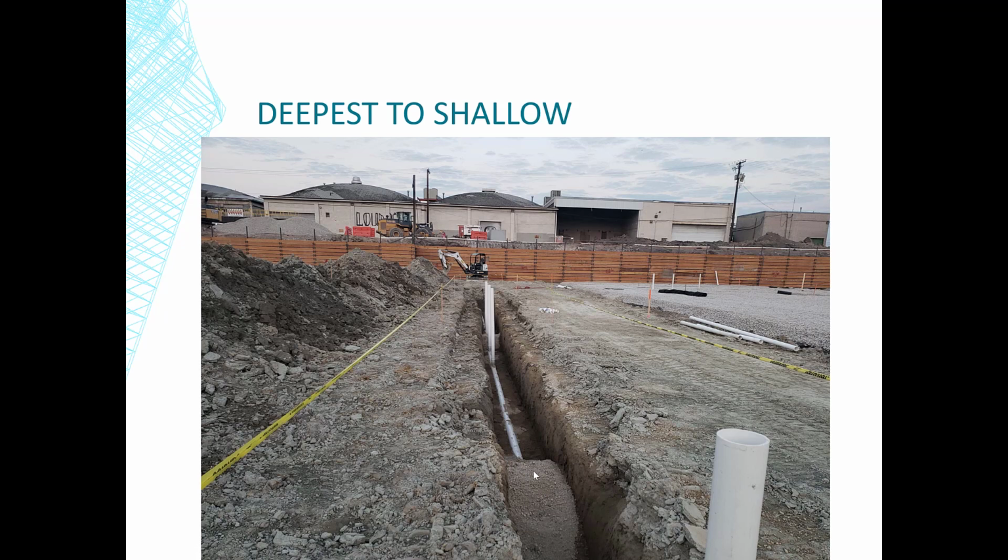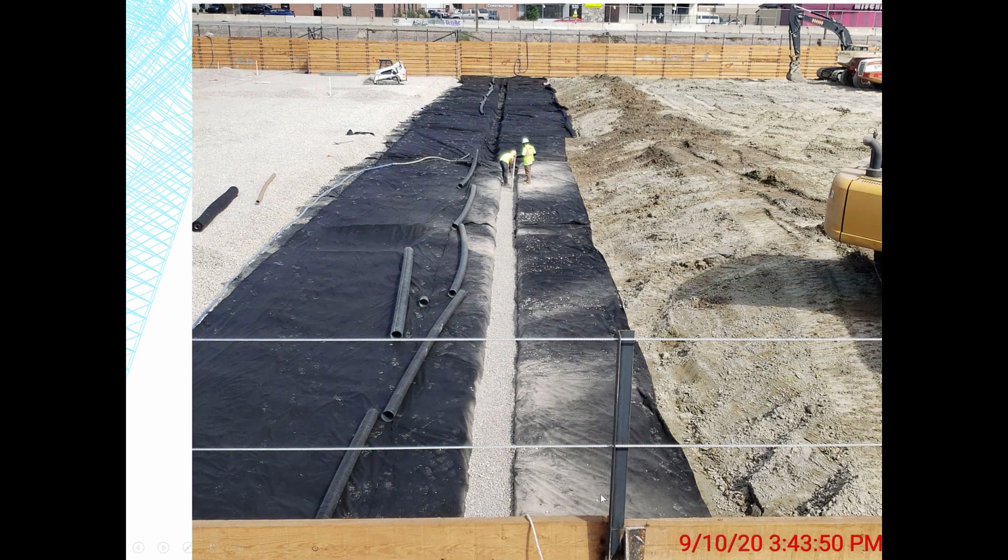But you can see the construction sequence. They've been working in this photo from the right going to the left, and you can see the work progressing and getting to a point where they can now backfill this, bring it up, and bring the Mirafi over, and bring the gravel over, and they'll continue to stage. You can see that a little bit better in another photo here. That's a good photo right there.